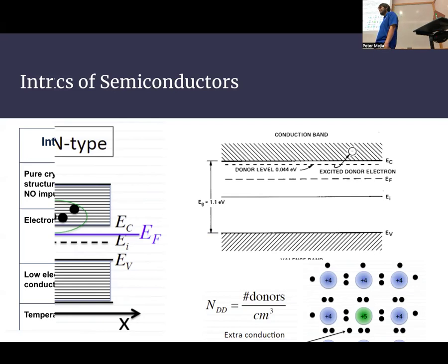Is it basically the Ei line after you add the dopant, the line that changes? It does change with dopant, but generally, what is the Fermi level? It depends on the dopant, and is also temperature dependent. It's like an average energy. It's close.